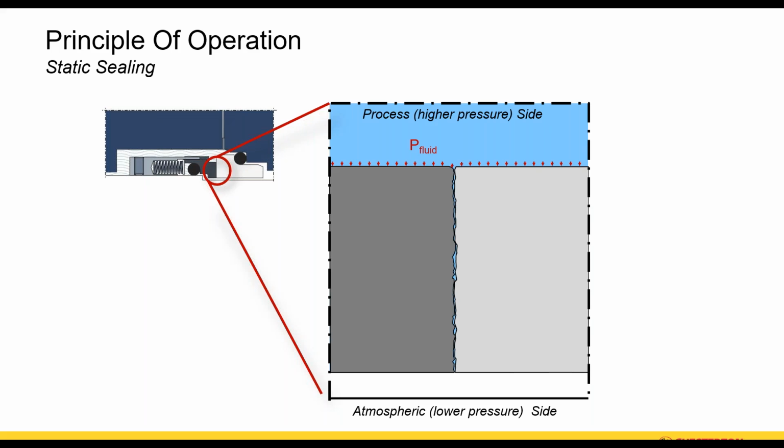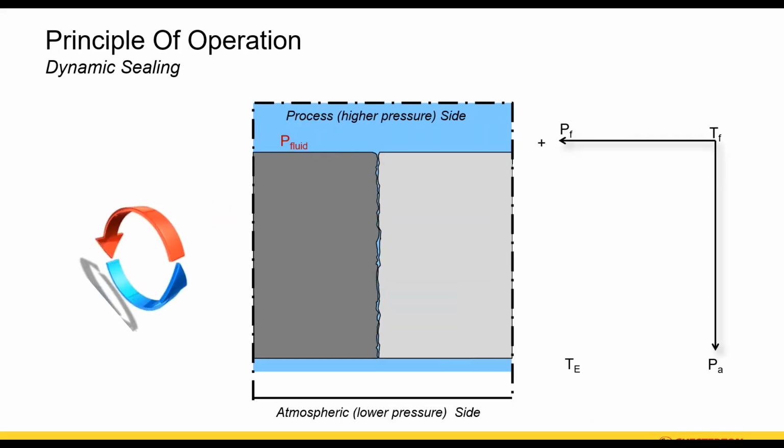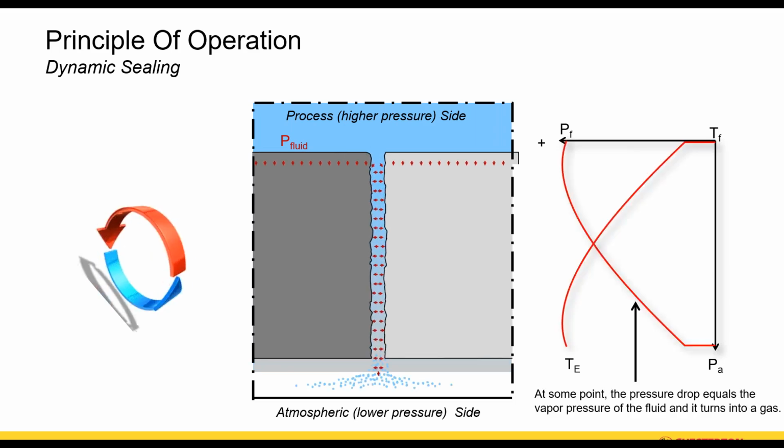And what happens is once rotation starts, the faces will actually open up because a fluid wedge is developing in that interface. Within that wedge, the fluid coming across those faces experiences a pressure drop as it comes across the face, but there's also a temperature increase.